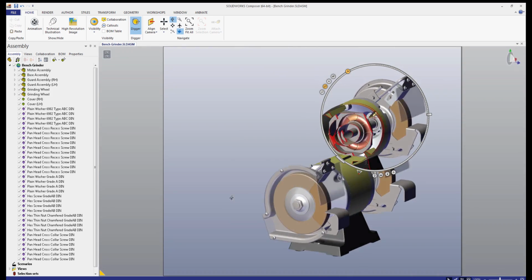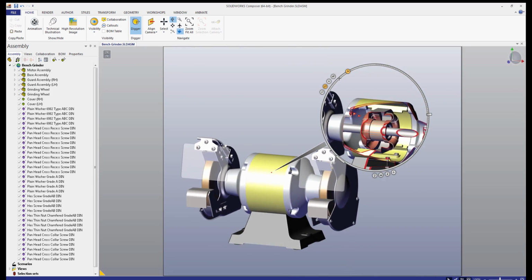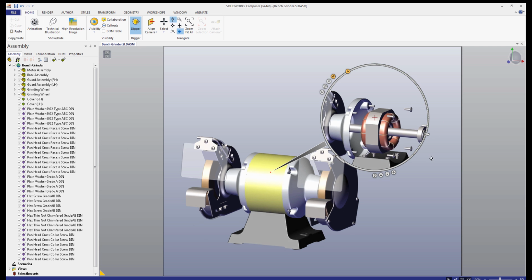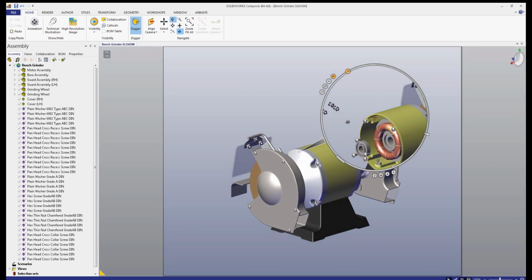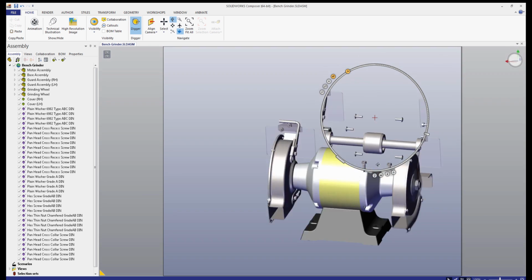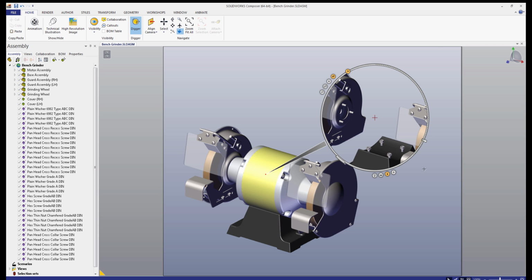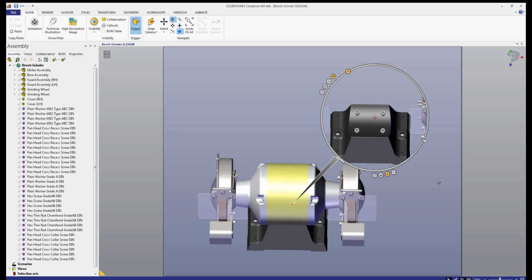This is the case for each of the tools we've just covered, as you can see here with our onion skin tool. But if we want the depth of our cut to remain static, how do we do it? We click the lock button at the bottom, scroll to our desired depth, and now if we move the camera, the depth remains the same while the view changes.